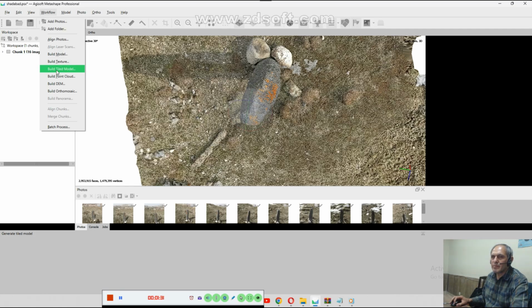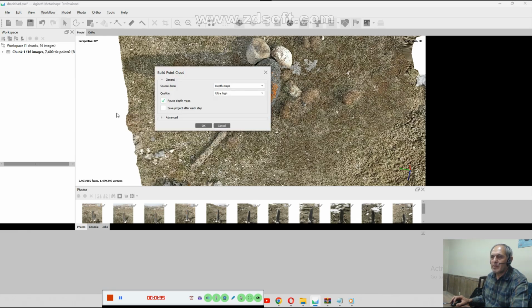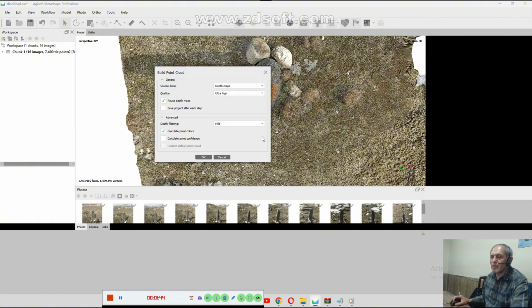You will finish. No need to create the DEM, digital elevation model, and it will automatically create the number of polygons, actually triangles. It's a kind of TIN, because as you know, each plane surface can pass through exactly 3 points, but not through 4 or 5 points.